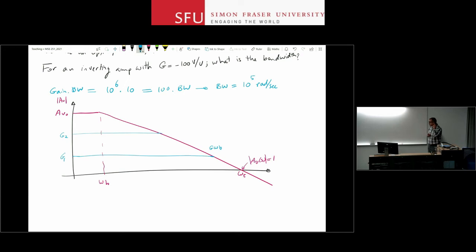So if you pick up an op-amp that has, let's say, a 1 megahertz ωT, and you want to amplify a 10 kilohertz signal with it, you should know right away that you cannot really get a gain of more than 100 out of this. Actually, 100 is probably not even true, because that's exactly the corner frequency. So if you need a lot of gain, let's say a gain of 1,000, you definitely cannot use a single op-amp anymore.